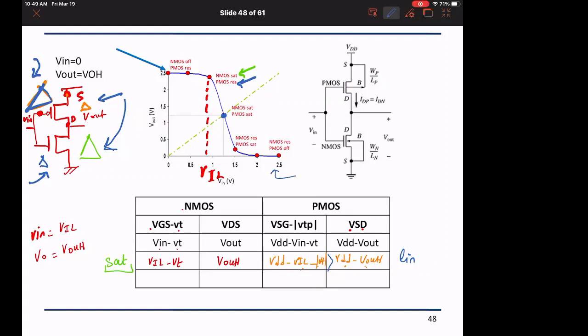Okay, so I want to make it just clear once and for all, where the PMOS turns off and the different regions of operation. As you notice here, the NMOS will start off in saturation because the output is high, it has a large output, and then it will turn to linear when it turns on strongly and it pulls the output down to low, to zero. So the NMOS becomes linear when it's pulling down strongly, and the PMOS is linear when it is pulling up strongly. We will see when the PMOS turns off and summarize this section next time.